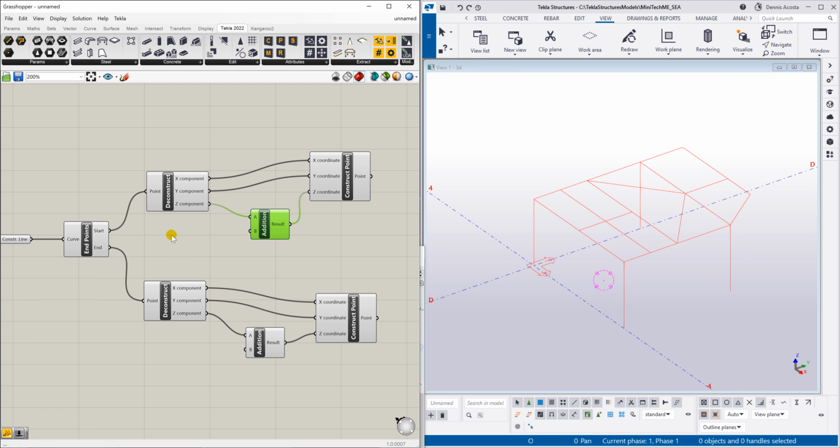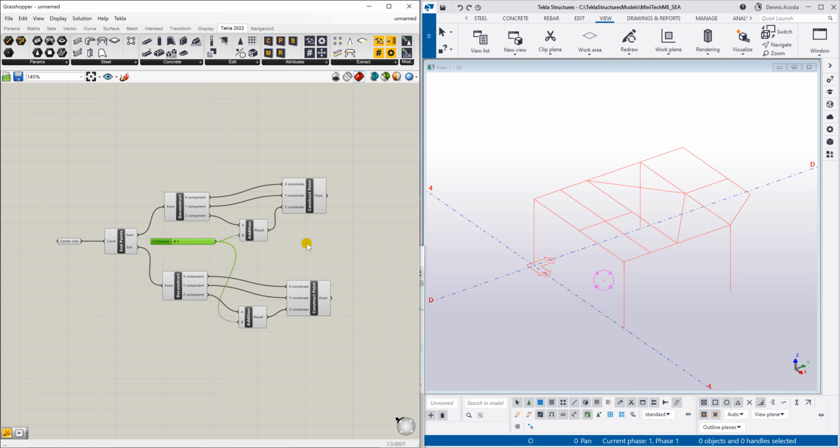So here I'm going to add a slider, and then I'll put here 0, let's say up to 5 meters. And then I can rename this one as the Z direction. All right, and then now link this one here to B and to B here. So if I add a value here in the Z direction, then it will either go up or down, the position in the level of the particular element.